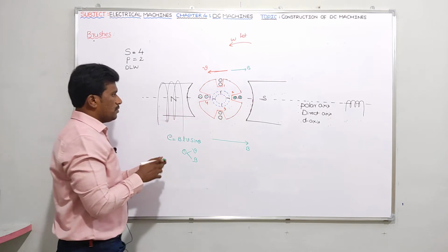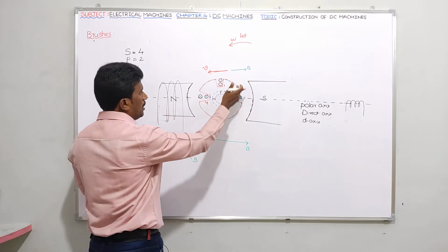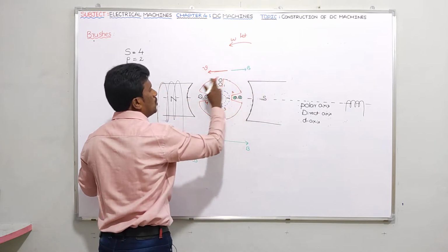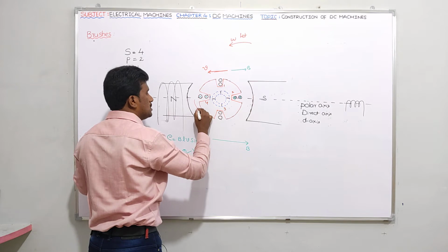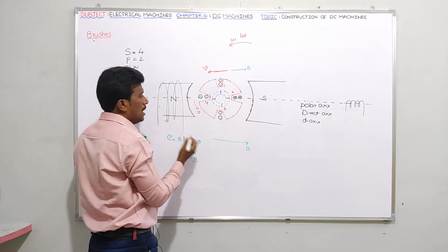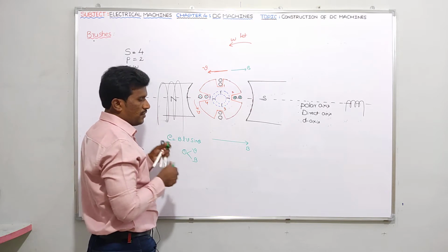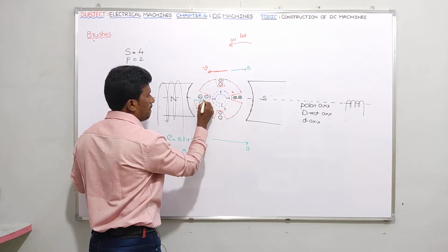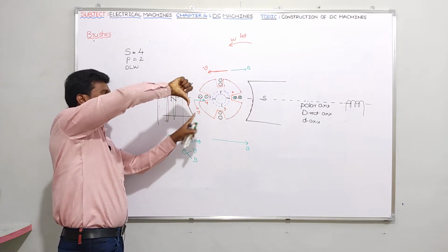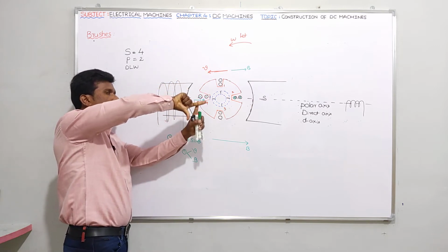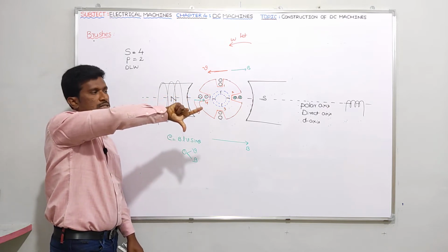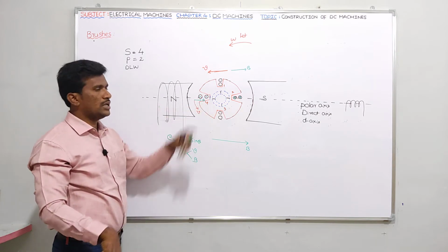Similarly, going in the anti-clockwise direction, after slot number 1 you go to slot number 4. Here this is the tangential motion, the velocity of the conductor, and the flux density is like this. Please apply Fleming's right hand rule once again. For a moving conductor, the thumb indicates V, the forefinger indicates the magnetic flux density, and the center finger indicates the induced EMF. Out of the board means a dot. That one I just showed.